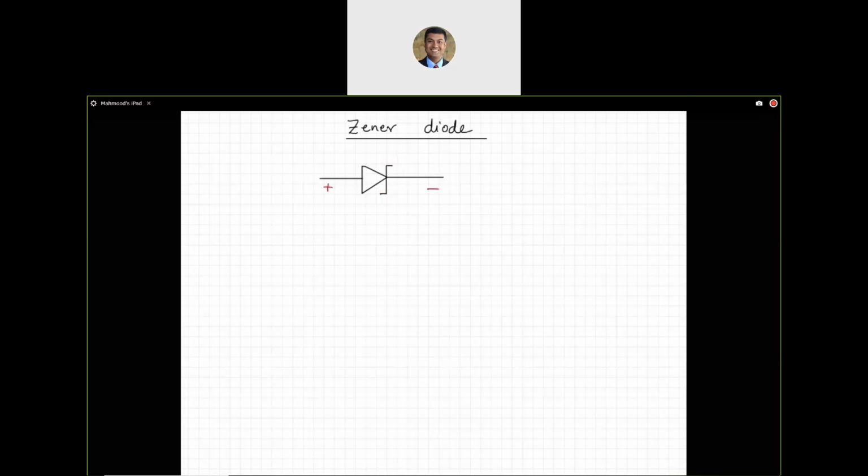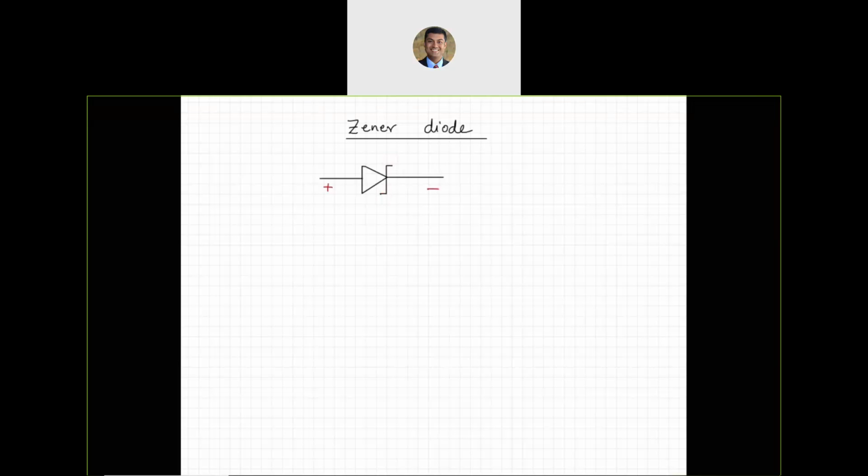But in terms of operation, a few things change here. So for example, if I take a look at an IV characteristic of this particular diode, suppose I have VD indicating voltage across the diode on the x-axis. I'll use VZ for Zener voltage. VD and say ID, so current through the diode versus voltage across the diode. So this is going plus and minus VD here, and the current is say ID here.